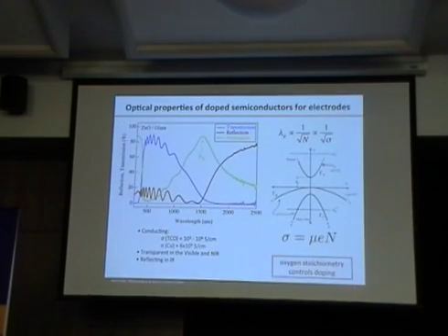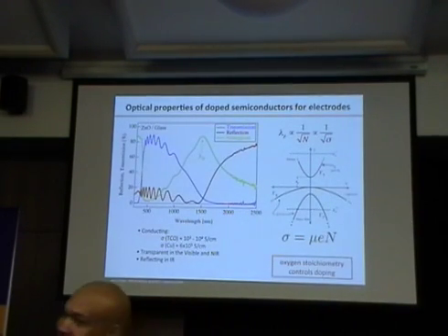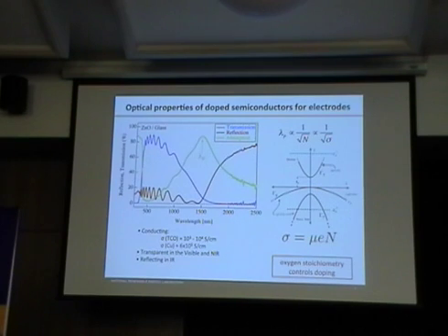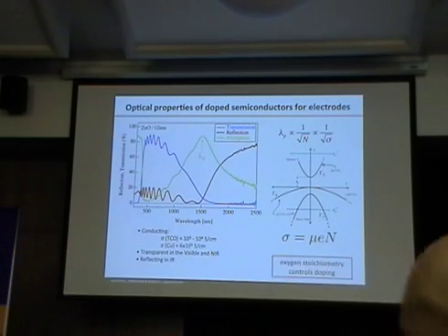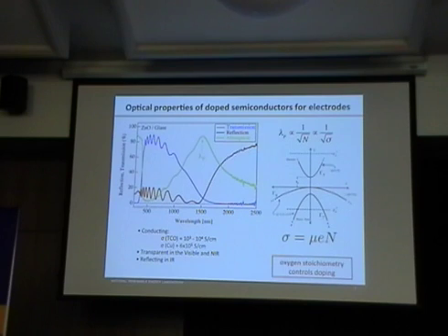All right. So we also looked at this, right? And I tried to convince you that when we're talking about these transparent contact materials, electrodes and contacts in this context, we're talking about basically semiconducting systems, which we do the normal semiconducting games in, right? If we need it as an electrode, then we want to dope it heavily so that we can carry current.